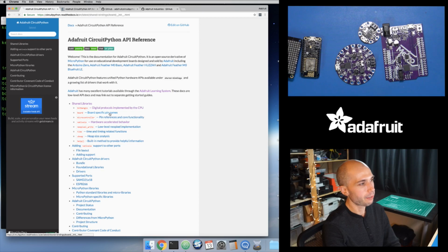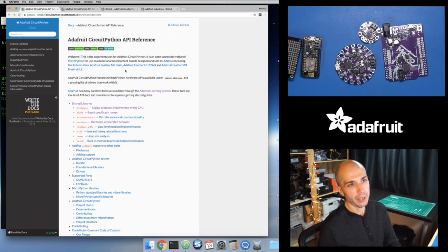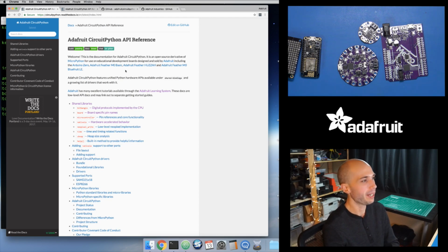And then the board module is kind of an interesting one. There's not a lot of documentation for this, and I'll show an example of what's interesting about it. But basically, again, we want to make this a little bit easier for beginners. On a lot of the MicroPython boards, you have to know what the pins on your board are, and you have to address them sometimes by a string, on some boards by a number. Sometimes that number is the board GPIO number, sometimes it's a physical pin number. On the Raspberry Pi, for example, there are all different types of pin layouts. That's really confusing and can be problematic, especially for beginners. So the board module basically has pin instances as high-level objects, and I'll show you why that's interesting and why it makes sense to do something like that in a moment, when we look at an example.